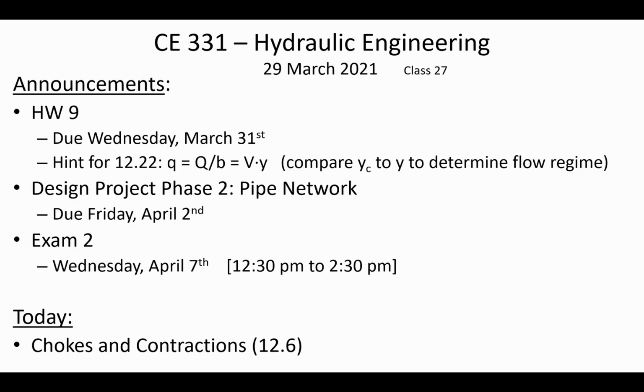And you should be close to the edge. That's efficiency, remember, the idea that you're just barely making the system work. That's the optimal design, as long as the criteria that you're setting are acceptable criteria. Then at your design flow rate, you don't want to have 500 kilopascals everywhere in the network. You want to have as close to 240, which is the lower limit, as is possible.